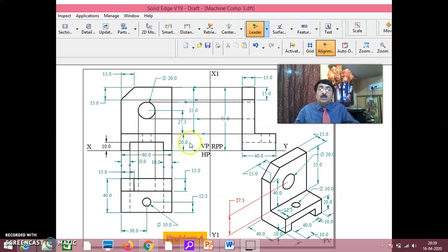Okay, now once you do this, more or less the front view is completed except this fold in the front view. I'll tell you how to exactly do that. Now once the front view is completed, come to the bottom. This distance can be anything, as I said. Whatever is this distance, you take this distance also, same thing. You take some distance here. It's some 30-40 mm, you leave it off. If this is 40, you leave 40 here also. If it is 30 here, leave 30 also.